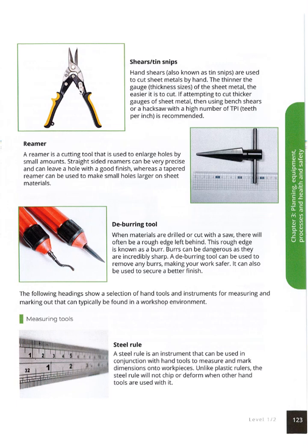Reamer. Now, a reamer is a cutting tool where you twist into an existing hole to make a hole on a piece of metal bigger. So you twist it, and ever so slightly, it will make the hole a little bit bigger. As you can see, it's got a pointed edge. So the lower down it goes, the bigger the hole becomes. This gives it as well a really good finish.